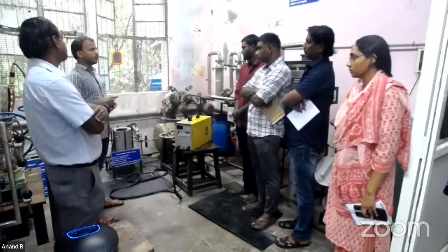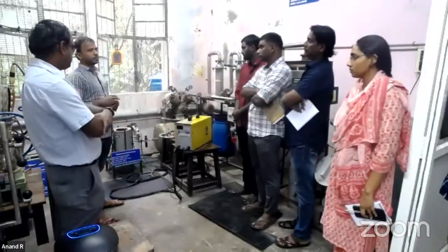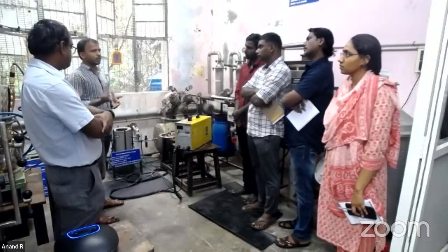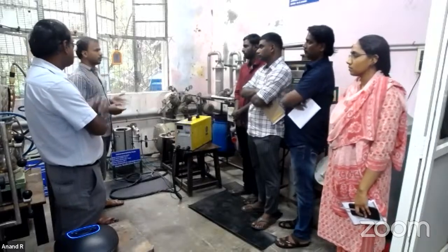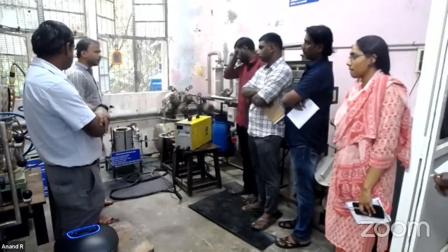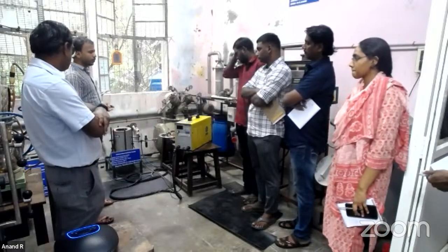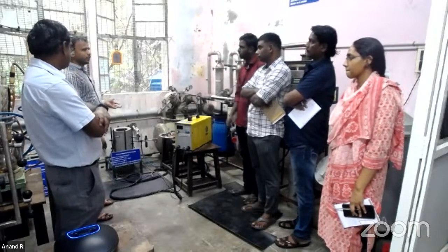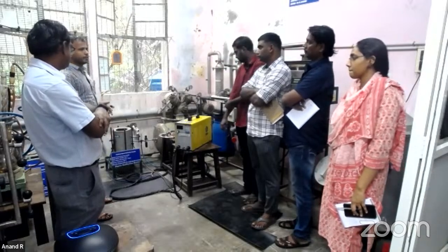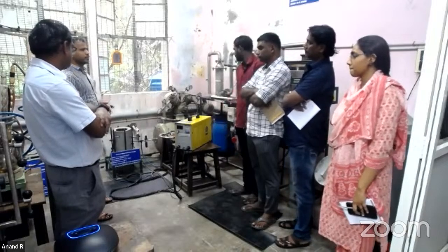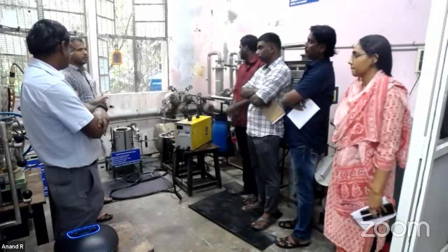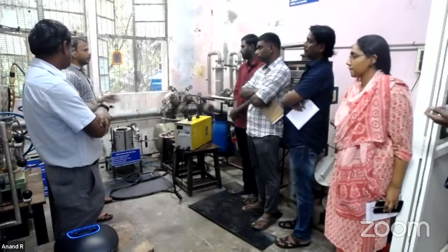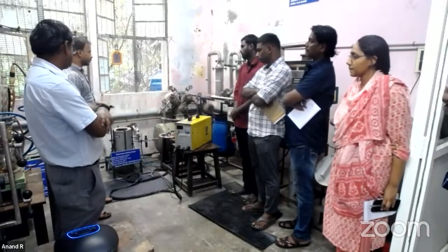For our case, it may go beyond 99%. If you put 100 gram solid waste, it will convert it into 1 gram of solid residue. So that much complete degradation happens. If you go with pyrolysis or gasification, the solid residue may be 5 to 10%. But for this case, it will be very minimal. For incineration also, we will get around 6 to 7%. Some unburned material may be there, but here it won't exist.